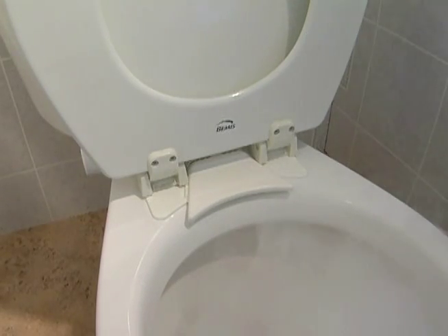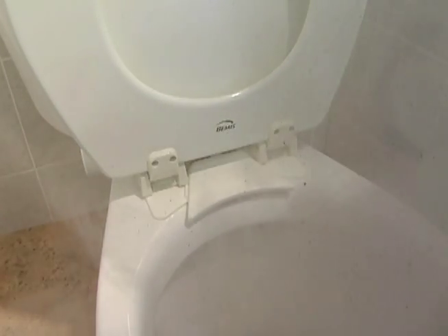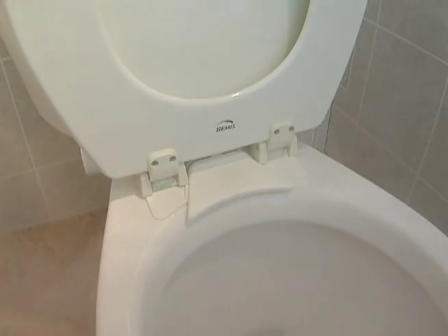In conclusion, based on these tests and field knowledge of this device, the data shows that the TVS device would do a much better job of removing odors than a standard ceiling exhaust fan. Data also supports that users should be able to reduce air exchanges by 1/4 to 1/2 over conventional restroom exhaust methods with no sacrifices in air quality.